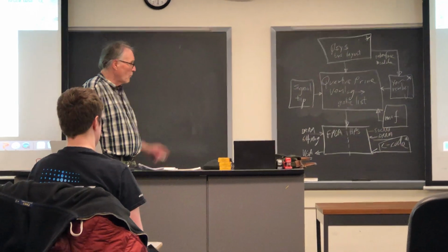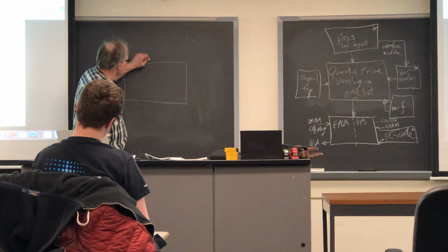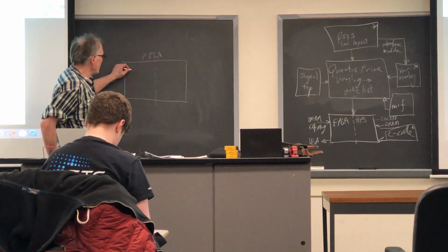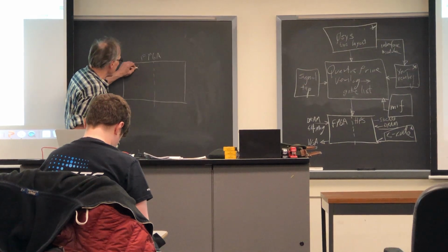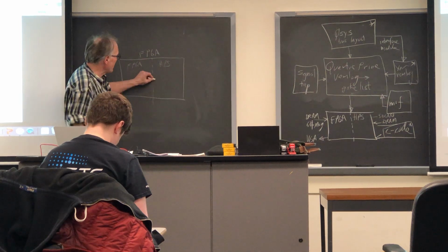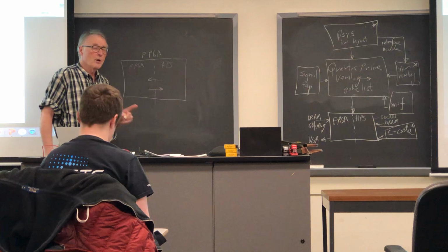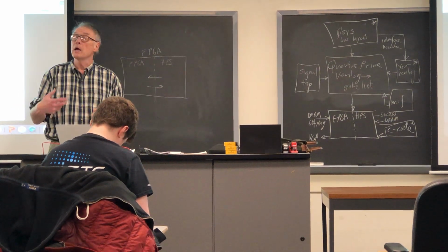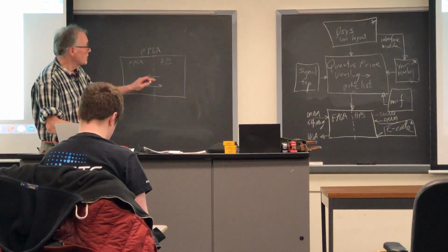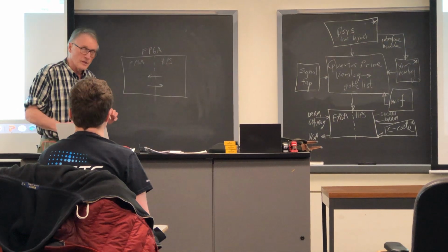So, one further detail is that the FPGA, which I divided into FPGA side and HPS side, then has a memory map across this boundary. A memory map which associates structures in HPS memory to locations on the FPGA side. There are two buses.